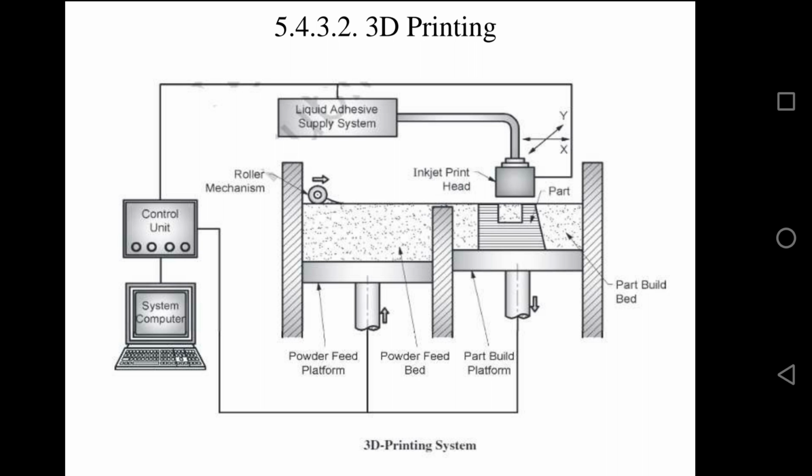So where do we find the applications of the 3D printing process? In concept models. If I want to make molds, I can make the mold by using 3D printing. And if I want to go for functional models, what are functional models? They are used for making parts from composite material for functional testing. For example, silicon carbide is infiltrated with molten material to make a composite material part. There I can use my 3D printing process.